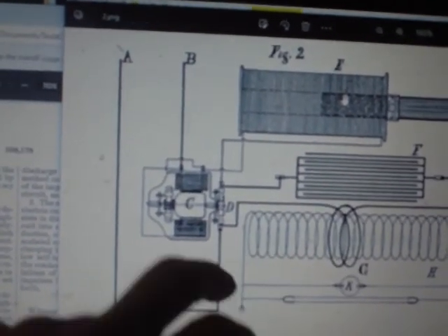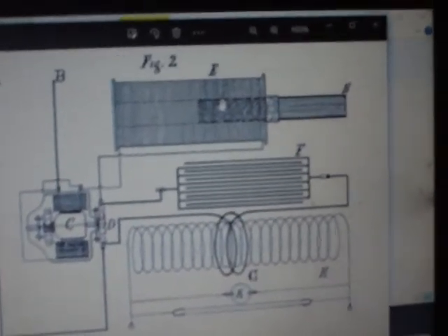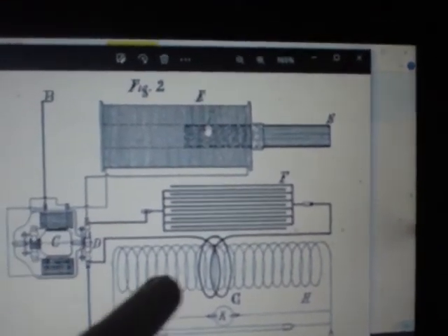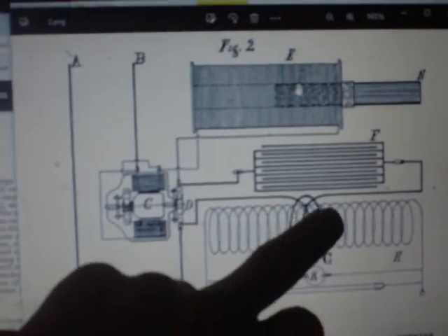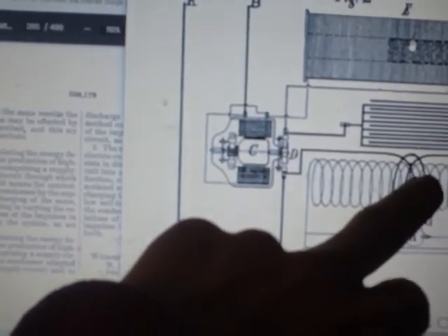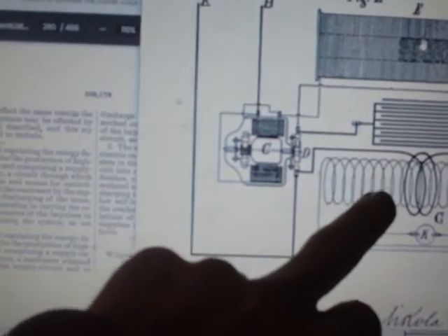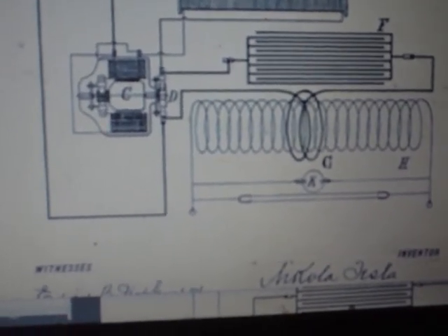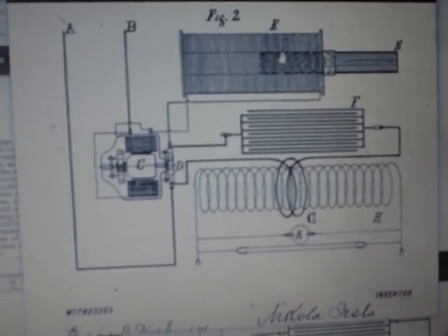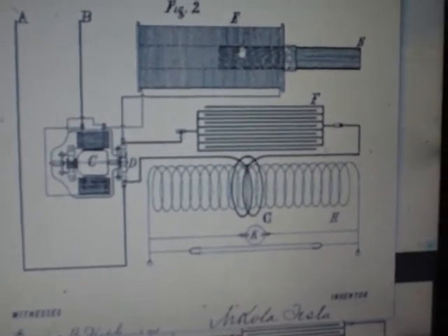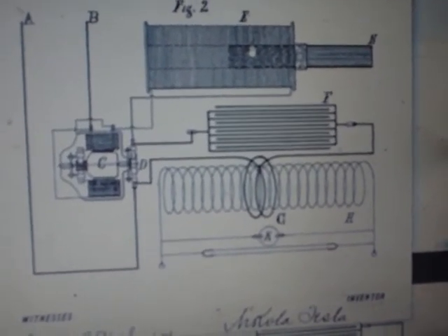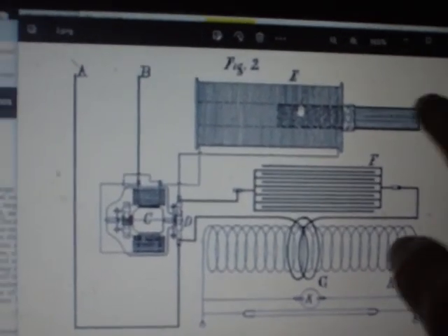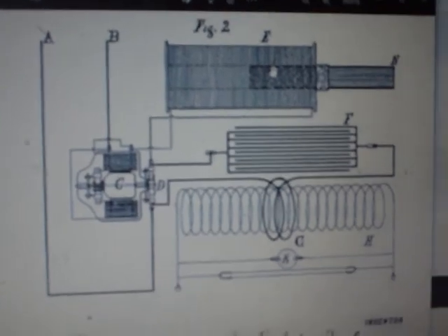And then of course you want to have everything in resonance, so you check the length of your wires, especially the primary. So this should be a division or a multiplication of your primary, and your primary is also in resonance with your secondary. All divisions in length of wire. And normally it probably is not so easy as that, but the nice thing here is that you don't have to have measuring equipment, because you can do everything yourself by adjusting the parameters.